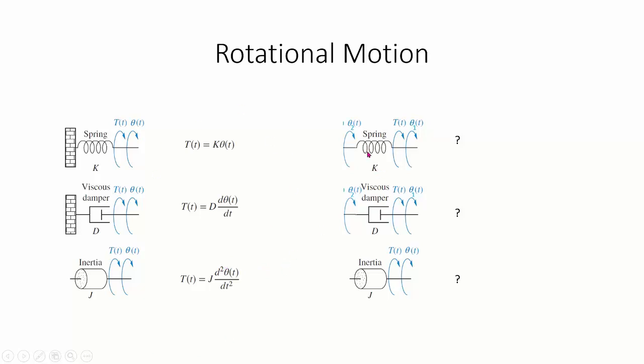And I told you it's supposed that both the ends are free to move in all the cases. For inertia, the mass is rigid, so you don't have both the ends free to move, because you assume that the mass is not flexible; it's always rigid. So in this particular spring, suppose that you applied torque on the right hand side, and this torque allowed the right point to move by an angular displacement of theta1, while the left point rotated by a displacement theta2.